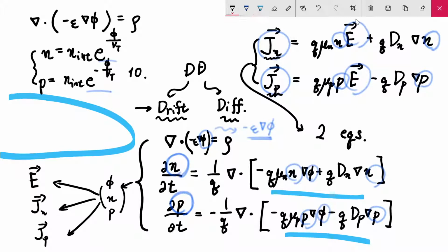So what will be the unknown variables in our case? Here we have of course electrostatic potential and electron density and hole density, and say that you are working with, for example, FinFET simulation, or in some cases you can also try, for example, even more advanced one, CFET or something like that. Then you feel that, okay, here we have strong quantum confinement, then those quantum confinement effects should be considered in our simulation. Then how can you do that?